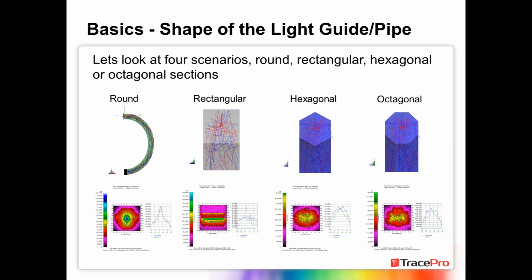Well, with the hexagonal type section, the light goes from one surface side to another surface side and mixes the light up fairly well here. And you can see that in terms of light output. We no longer have that peak. It actually is sending the light out and mixing it so it comes out in a more uniform manner. The efficiency is about the same, no big problem there, but the light output is now much more uniform on the exit surface. So this is a good way to change the shape and mix up the light a lot better if we're trying to do a bend.